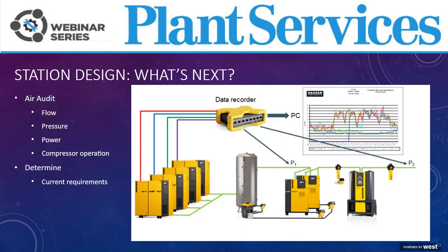Now that we've spent some time within the compressor room observing some key points, let's talk about what equipment we've actually got in there and whether it's the right stuff or not. How do you determine that? An air audit measuring flow, pressure, power, and compressor operation is going to help you determine how much air you're using now and whether it's operating efficiently and effectively.